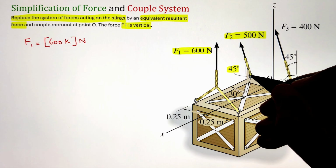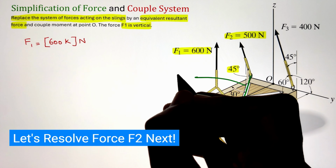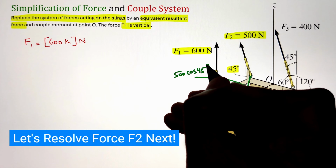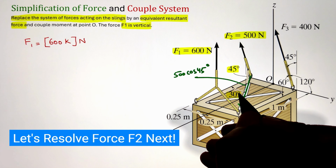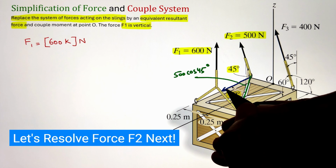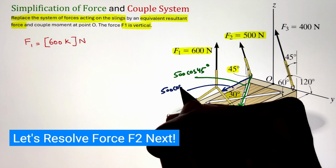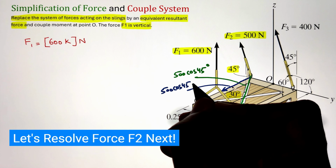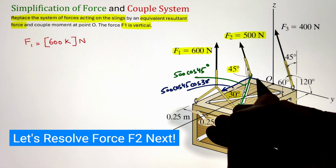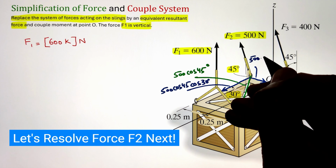Next, I have a force F2 that is making an angle of 45 degrees with the XY plane. So taking the cos 45 function will project the force onto our xy plane. Next, this line is making an angle of 30 degrees with respect to the x-axis. So taking the cos function again is going to project the 500 cos 45 force component times cos of 30 along the x direction. Similarly, if I take the sine 30 function, it is going to project our 500 cos 45 along the y direction.